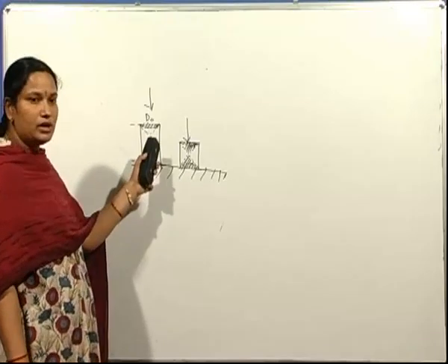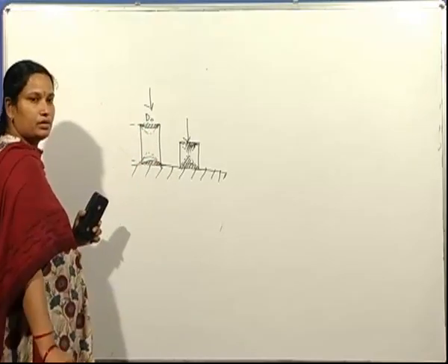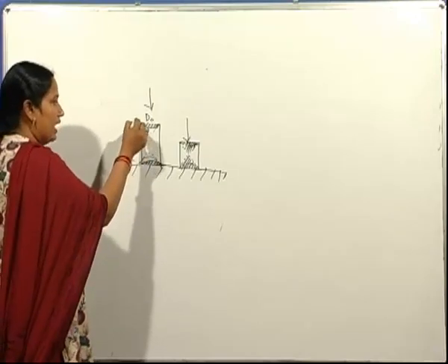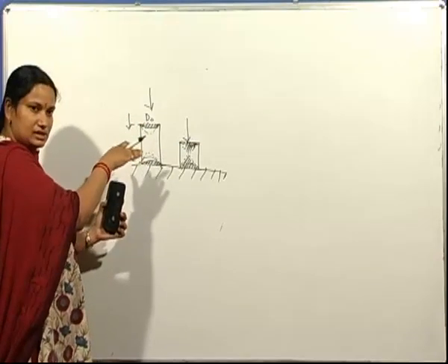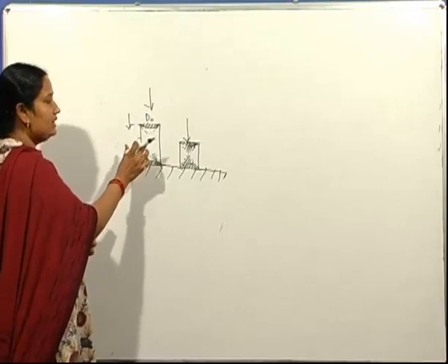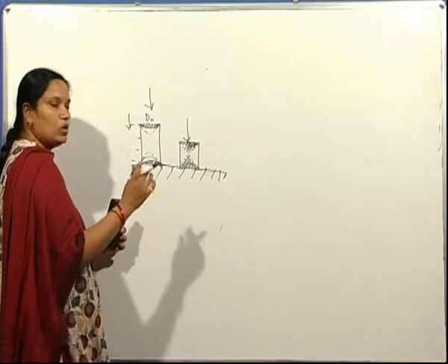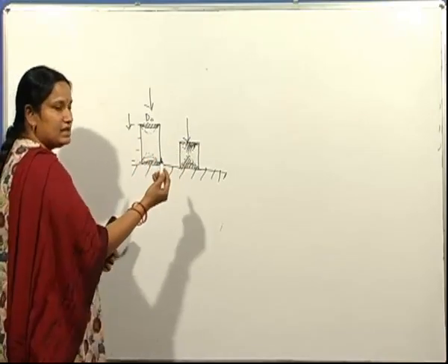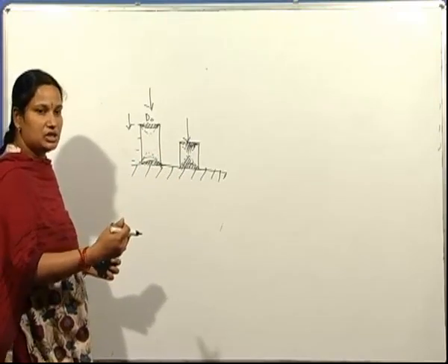Whereas in the case of longer specimen, lesser is the undeformed region because the specimen height is more. Thereby, as the reduction or the compression takes place, these two regions do not overlap in the case of longer specimen, whereas in the case of shorter specimen, these two undeformed regions overlap and increase the stress required for further deformation or further reduction in height.